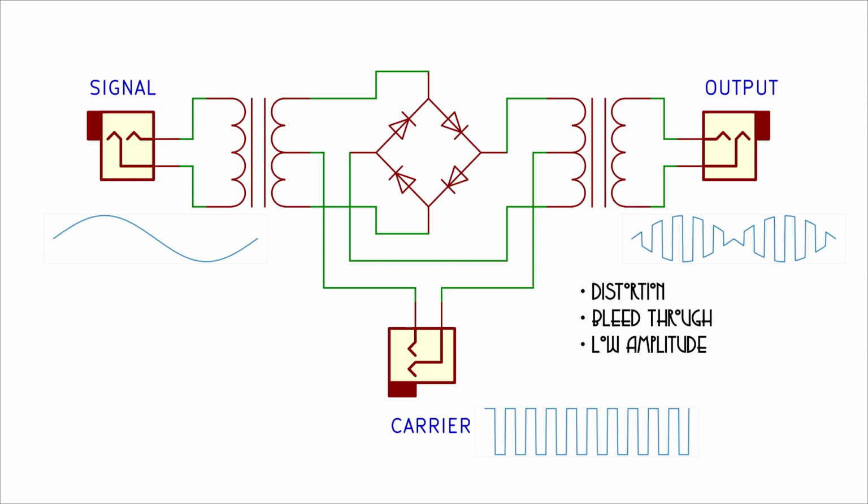And they sometimes refer to these circuits as balanced modulators or 4-quadrant amplifiers. Then again, sometimes they just brazenly refer to them as ring modulators, even though pedantically and prescriptively only something with a diode ring and transformers ought to be called a ring modulator. But they pass these other circuits off as ring modulators anyway. Not naming any names.